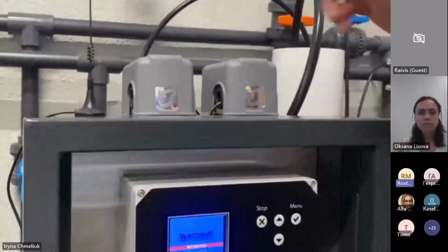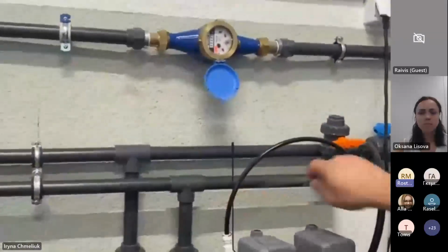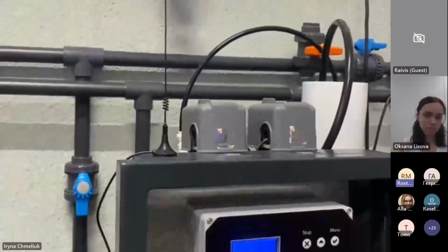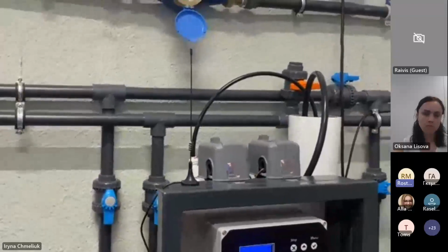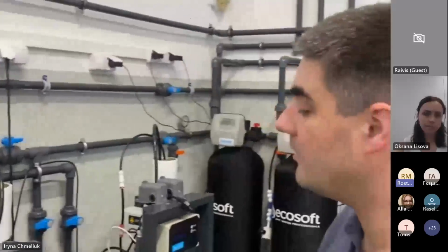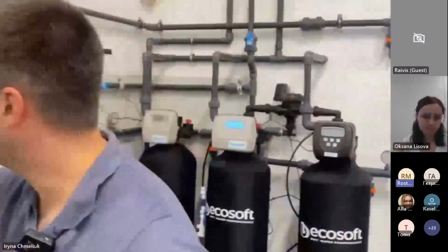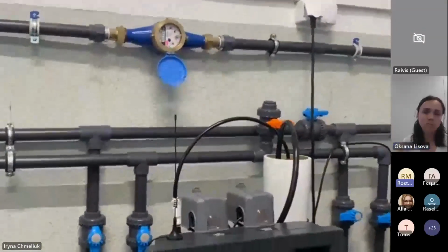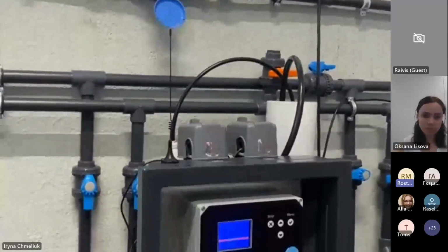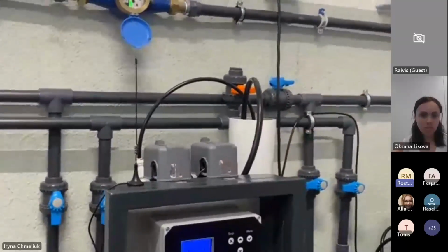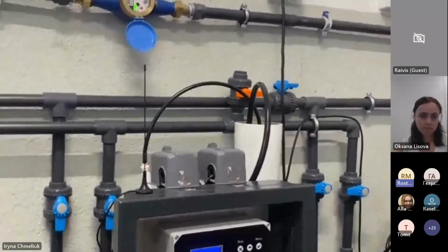Also, if the permeate line is also made with the flexible hose with the 3/8. Sometimes the plumbers do the 3/8 connection or half-inch connection. Then the system does not have enough flow on the permeate line, and the system is stopped by the high pressure switch. So actually you cannot switch on the system and make it running, because it is always switched off by the high pressure on the permeate line. So before you do the startup, make sure that the connections are made in the right way.